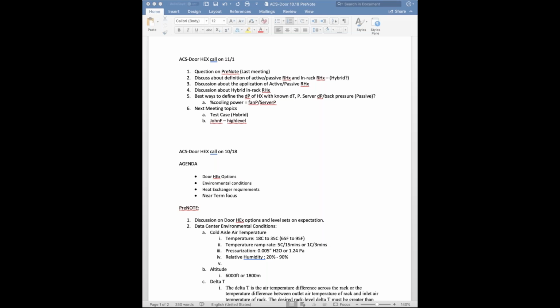That's rather difficult because that's strongly depending on the ambient. Can you run a system without chillers or not? And what's your energy cost? Because that varies from country to country. So in one country it can make sense. In another country you say I'm never going to do that because the energy is too cheap. So it's always something that has to balance between ambient and energy price.